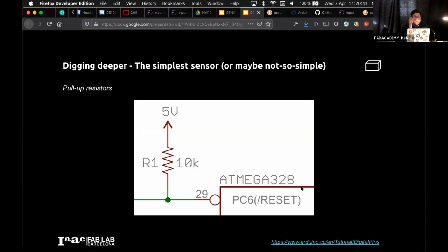In this particular case of reading a digital input that is either high or low, it is conditioned by what happens when I press the button. If the button, when I press it, goes to ground, then I want a pull-up. If I press it and it goes to 5 volts, then I want a pull-down, because I want to be able to differentiate both states. And in each option, I want to make sure that I know what I am detecting, right?